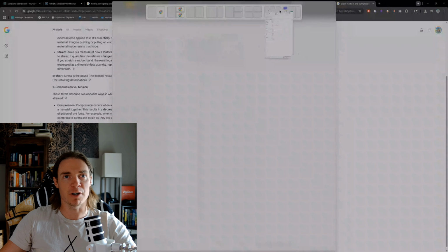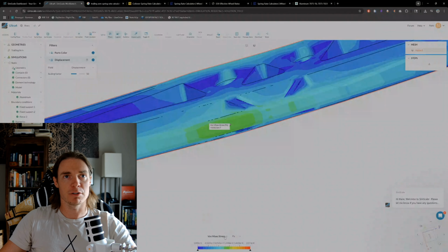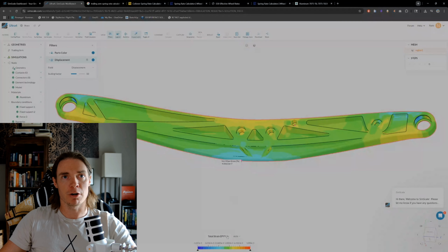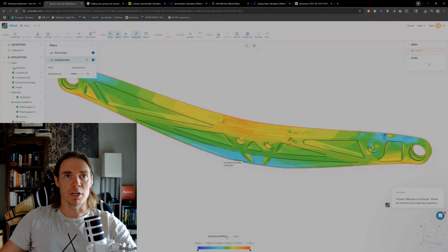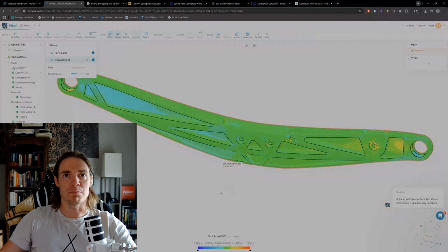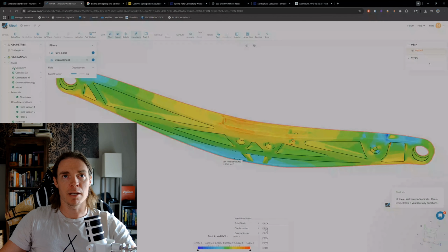Well, technically it's 5 times stronger than it needs to be, but I can knock that safety factor down by chipping away at this part. But this part was not that heavy. It was only about 100 pounds. And I mean, it's a 6-foot long piece of aluminum, so that's okay with me. And I'm not simulating any side loads on this. I don't know what those loads would be in terms of corner weight force, but I think the beefier, the better on this one. So now I found another hotspot here in that red.